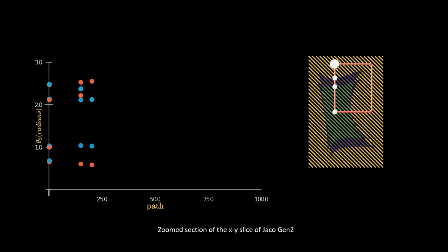and you can see that the blue points correspond to the solutions for whom the value of determinant of Jacobian is greater than 0, while the red colored points correspond to those inverse kinematic solution whose determinant of Jacobian is negative. We here are showing different important points along the path, such as when we cross the regions and as well as the vertex of the path. Notice here that as we are performing a loop in the workspace, it is expected that the initial inverse kinematic solution matches the final inverse kinematic solution, as is clear from this particular graph.